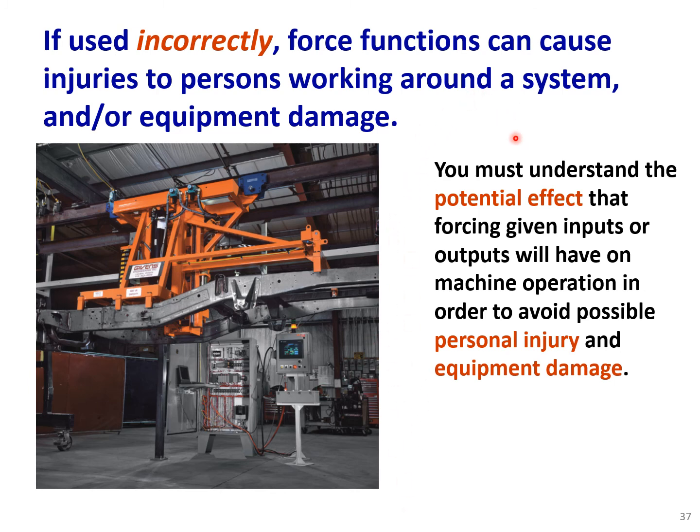If you force one input randomly, you don't know what the consequences would be, and sometimes it is better to avoid it in the online mode. Okay, so in simulation it is good. Usually they do the forcing in simulation because they want to check the performance of the program, but in online mode on the machine, it's better to avoid it.